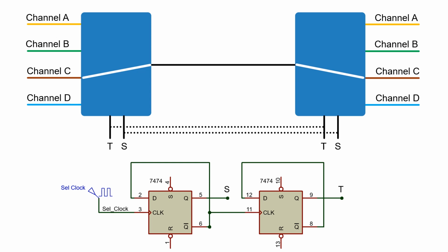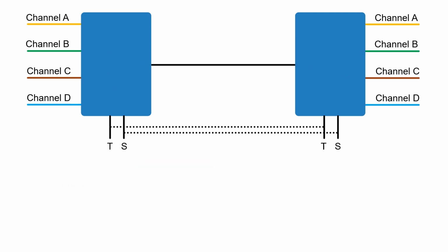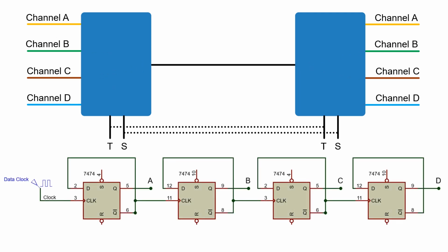I've included a really simple 2-bit ripple counter to control S and T, and I've created a 4-bit ripple counter just to provide some data to automate the data. This ripple counter will just count up from 0000 to 1111 and give us different frequencies for our data.